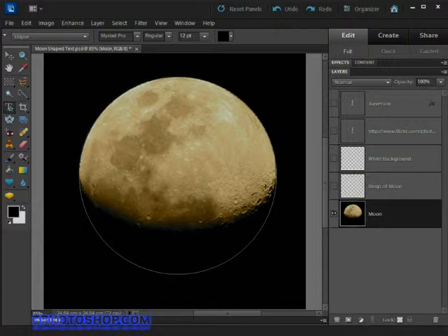By the way, that was one smooth operation I carried out there. If you depress the left mouse button during any of that, then your best option would be to start again. And you can delete the shape, by the way, by simply pressing the delete key on the keyboard. So what we've done is created a path outline. We can now add text to follow the path wherever it may go.